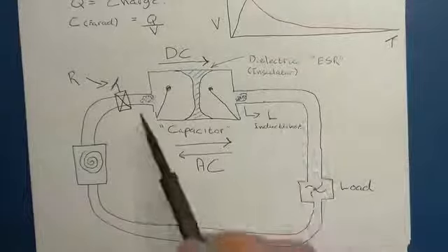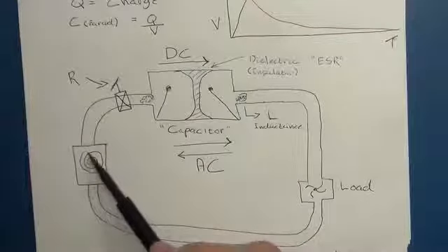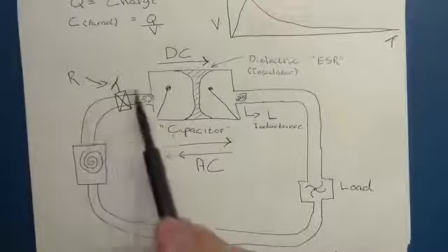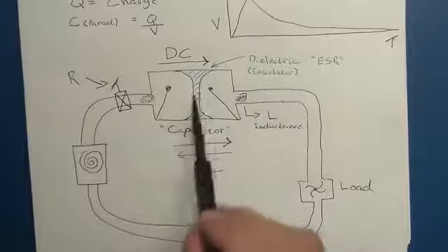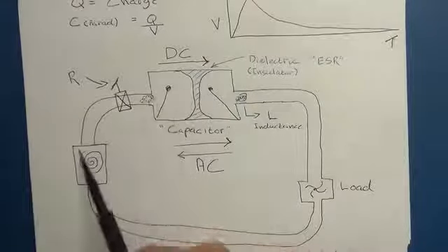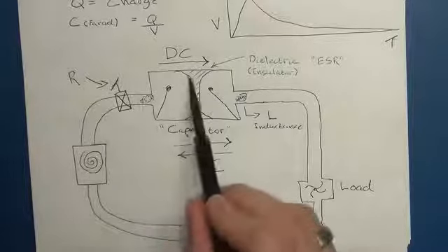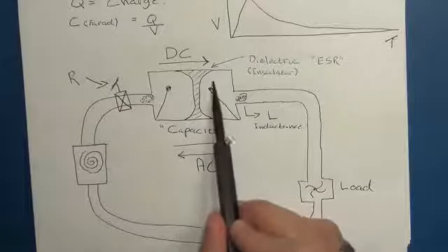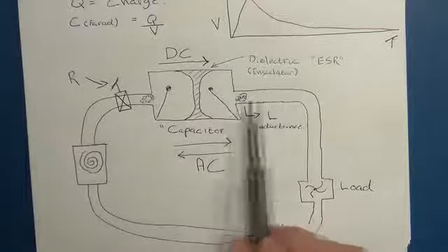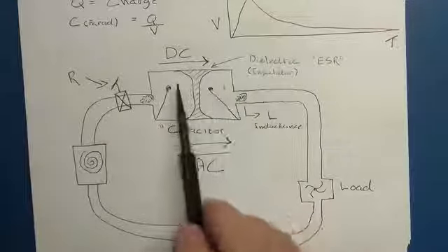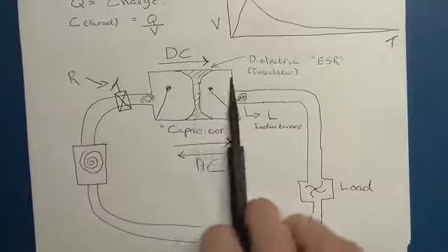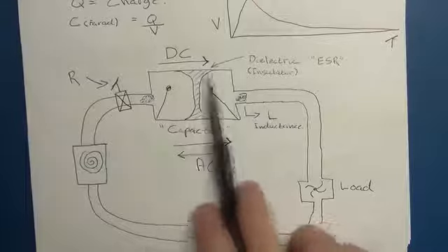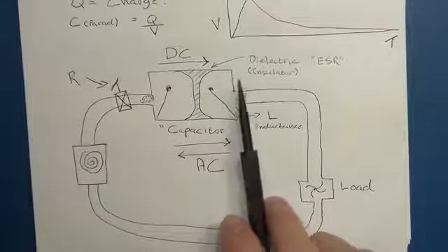Now if we picture that we put on our power source and we've got DC current, so DC is constantly flowing in one direction. What's going to happen in this scenario? The water flow is going to fill up this bladder, it's going to push, and as you can see, it's going to push water out the other side and allow current to flow for a while, because this bladder is going to push over and then block. This little gate or valve over here is going to block and stop once the capacitor is full. And that's literally how it works in an electronic circuit.